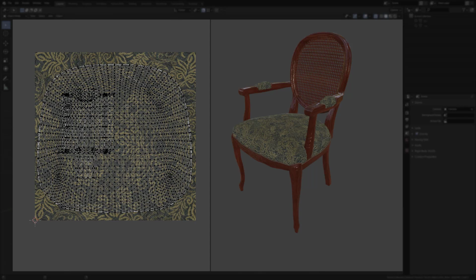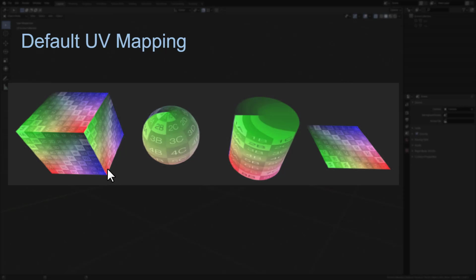A 3D model has within it information that tells a material how to map across its surface. This is referred to as a UV layout. When you create a material, you can map it to a UV or assign it a simple mapping method, often referred to as a projection. These simple projection methods typically include cubic, spherical, cylindrical, planar, and there are others.